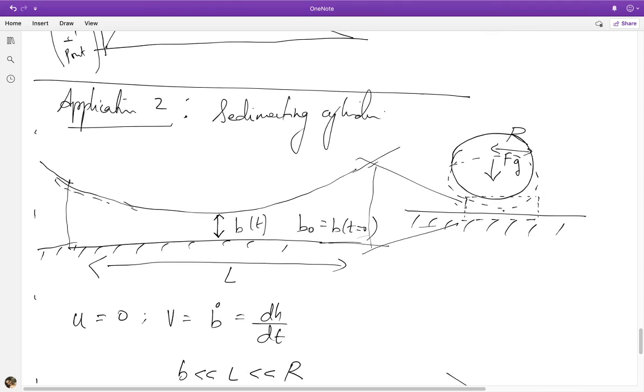I know that the motion of the cylinder is governed by the balance of forces. One is the gravitational force, the other is its own inertia, and the third is of course the viscous stresses and the pressure forces exerted by the fluid. But if we consider that we are in a Stokes flow regime, so that the cylinder is sufficiently small, so that we can set Reynolds equal to 0 and the Stokes numbers are small, then we can neglect inertial effects.